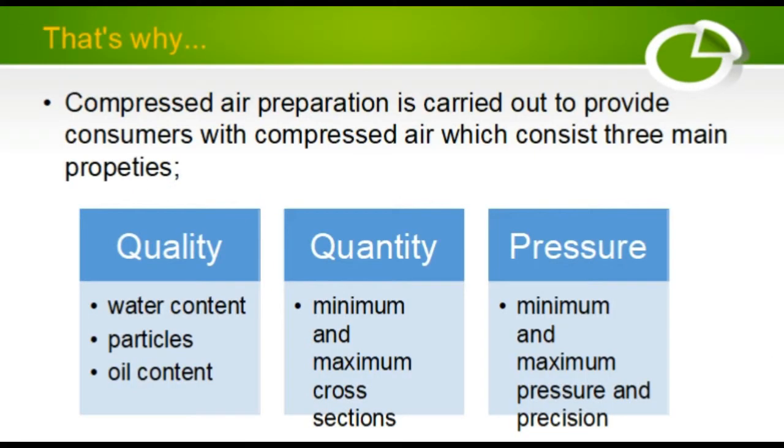That's why compressed air preparation is carried out, to provide consumers with compressed air which has three main properties, that is, quality, quantity and pressure. Quality is for water content, particles and oil content. Quantity is for minimum and maximum cross sections, while pressure is for minimum and maximum pressure and precision.